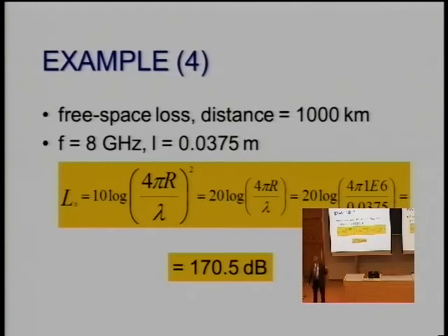It's free space loss. On the other hand, if our transmit antenna on the ground is a dish, and we go up with the frequency at the same size of the antenna, the gain of this antenna increases with the square of the frequency. So the two things cancel out. The free space loss and the additional gain of the antenna compensate.